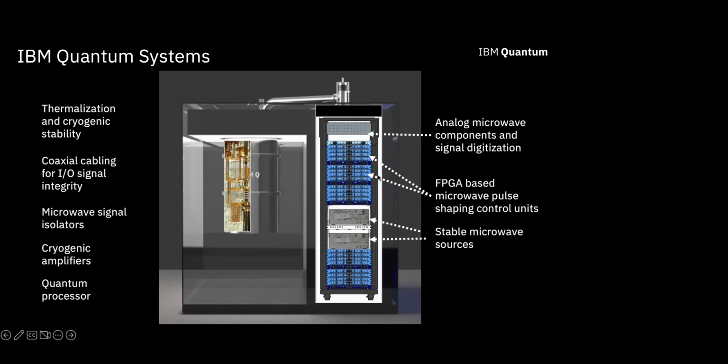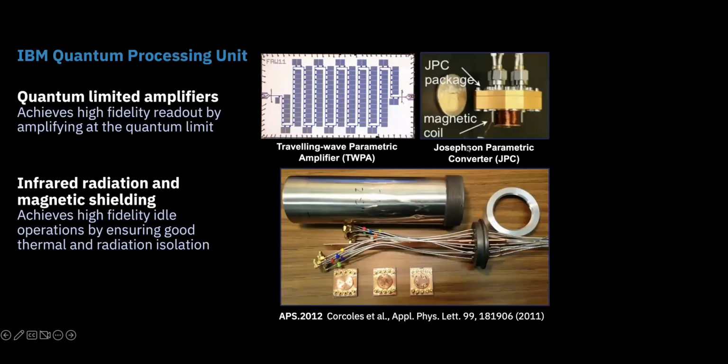And so one of the things you've got to do is shrink these kinds of things down, because we're building bigger and bigger systems. So some of the things that we actually spend our time working on in the lab, and some of the stuff I've had to do with, is looking at quantum limited amplifiers. These are a very special kind of amplifier that are also based on the Josephson junctions. In particular, the Josephson junction has this nonlinearity, which is very important, that we build an anharmonic oscillator out of for a qubit, but that nonlinearity can also be used to build amplifiers.